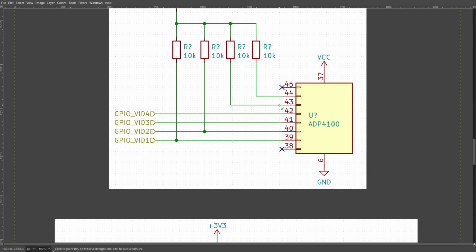It's simpler that way. So for instance, we already know that the GPU is probably not going to care about controlling vid 5 and 6 here. In most cases, we have a pretty set narrow range that we know the GPU is going to run the voltage at. We also don't need super fine resolution, most likely. Changing it by 6.25 millivolts, really not important. It doesn't make a big difference to the controller anyways. The 12.5 millivolts is probably enough resolution anyways.